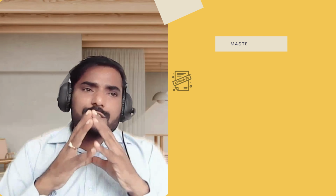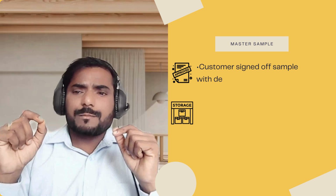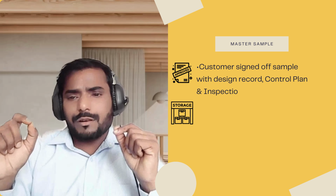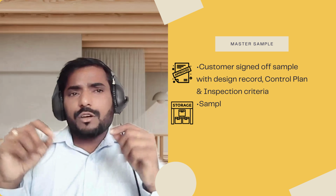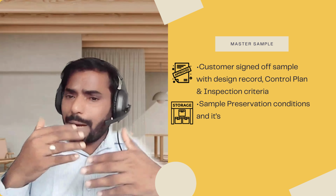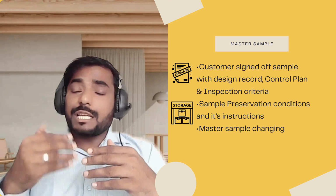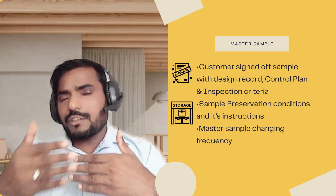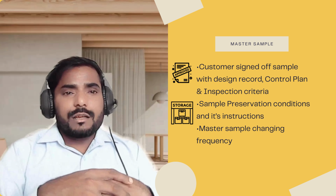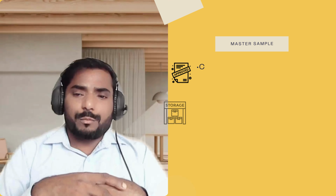Now talking about the master sample. So this master sample should be signed by the customer. And what is the preservation instruction for this master sample? What is the changing frequency? Because there are a few components which will get impacted from the environment over a period of time. So you should define the changing frequency. Let's say over like 6 months, there cannot be any impact on the component, right? So after 6 months, there can be an impact on the master component.